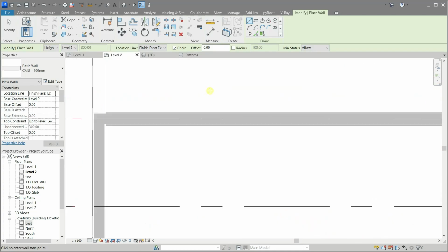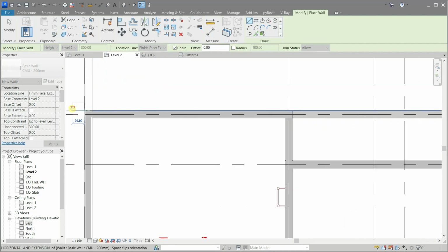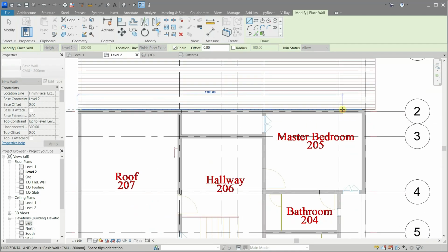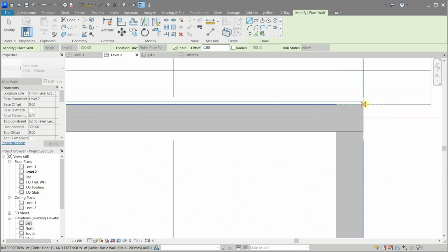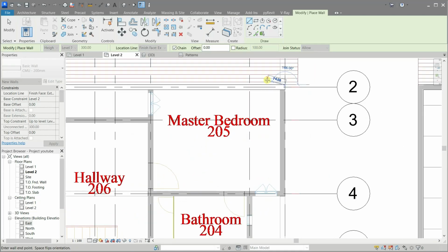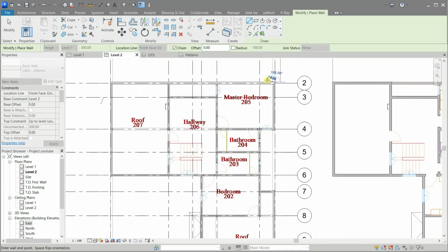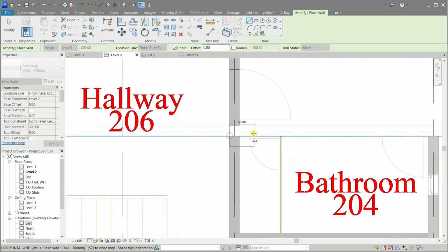By the way, the process of linking a CAD file in the Revit environment could be done with a PDF file too, at least in 2023 version. Also, you could link another Revit file to an existing Revit file. This is especially useful when working in a team environment, where some people are working on architectural drawings, while the others are working on structural or MEP drawings.